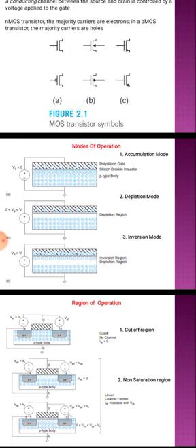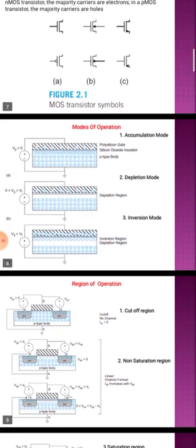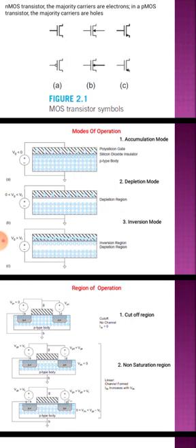to give some desired N-type impurity concentration. On both sides we are going to diffuse N-type impurities on the P-type substrate to provide some N-type impurity concentration. That region is nothing but the source and drain regions, and if we take some lead outside to connect to the outside world, it is nothing but the source and drain terminals.